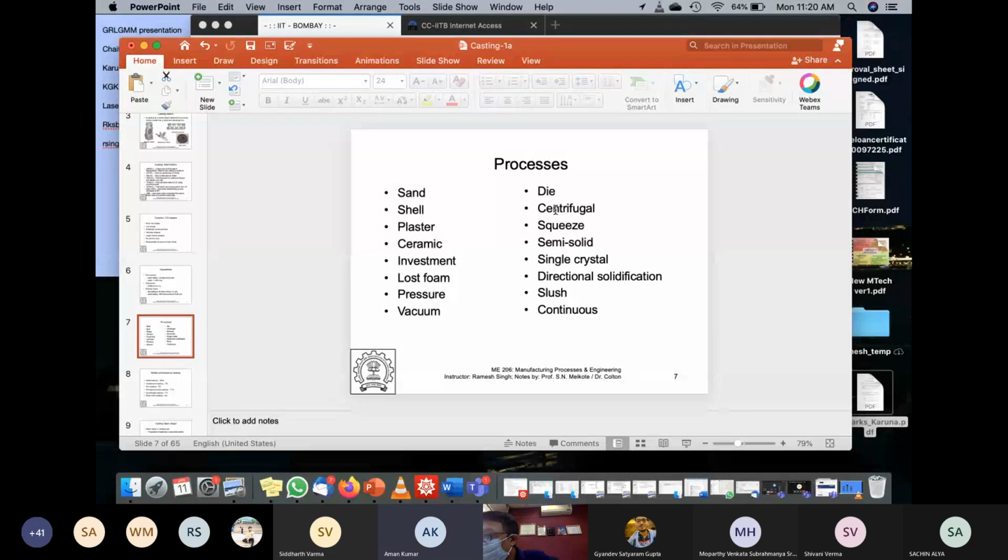So first a pattern was made with the help of the wax, and then we create a hollow thing. Why did they use wax? Sir, the wax is simply used for creating a pattern so that we can get the hollow substance after. Why not wood? Why wax? Sir, while heating it melts down and goes. Yes, so you want a low temperature thing.